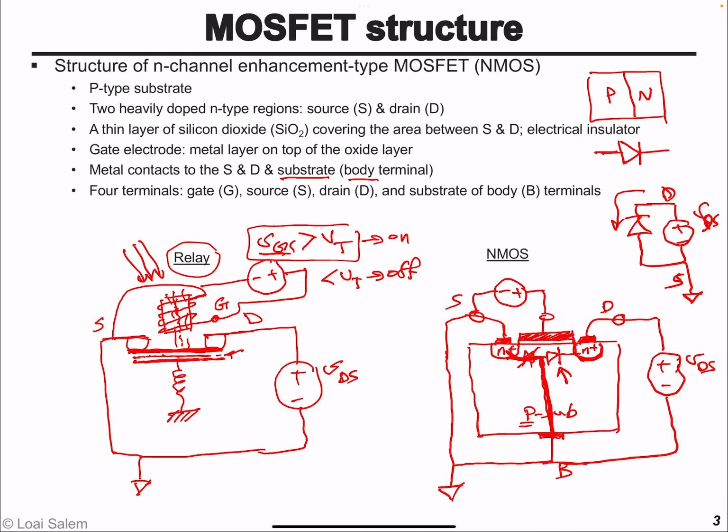Just like I mentioned about the solenoid that's wrapped around a magnetic core, the threshold voltage represents the voltage value that will cause enough magnetic field to pull the filaments towards the source and drain and cause shorting between the source and drain against the pulling of the spring.